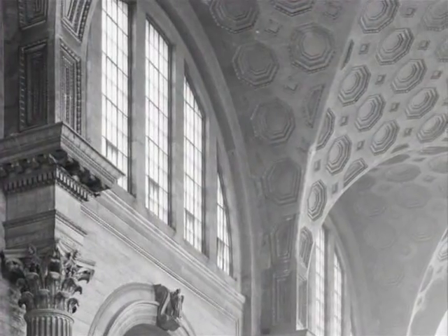First, they lightened the vaults by casting into them a grid of octagonal indentations called coffers, which you can see here in the vaults at Penn Station. The coffers might appear to be purely decorative, but they actually serve a vital structural purpose. In our lecture on arches, we saw that the lateral thrust of an arch is directly proportional to the magnitude of the downward load. Since the largest downward load on these vaults is their own self-weight, reducing the weight of the vaults causes a corresponding reduction in thrust.